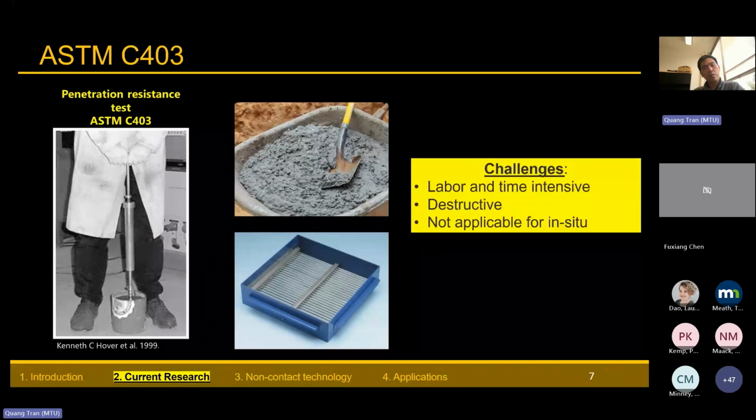However, one of the steps that we have to follow in this procedure is wet sieving. I remember when I did the wet sieving, all I did was shower the concrete into a big sieve, and then with the help of my friends in the lab, we held the sieve and kept shaking it, and then finally we collected the paste.